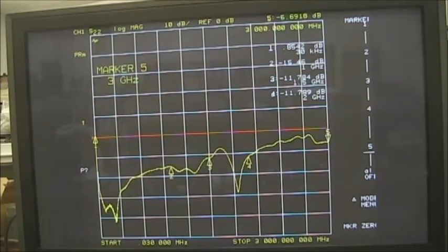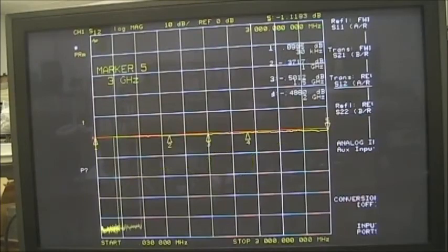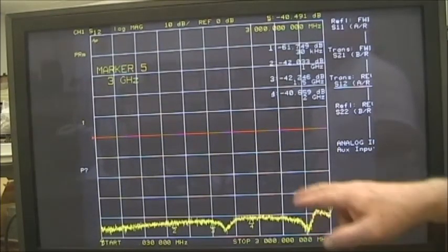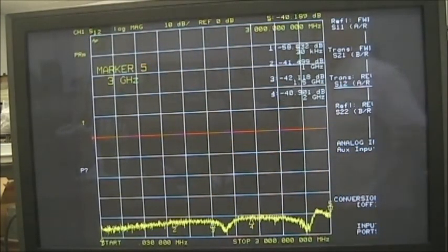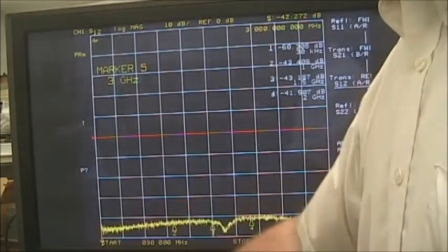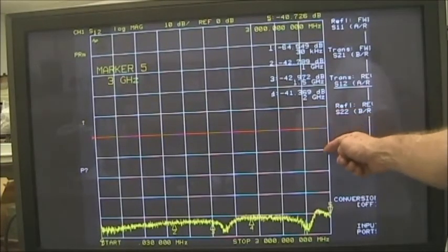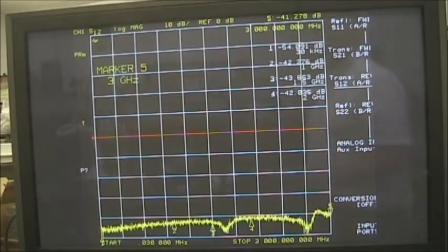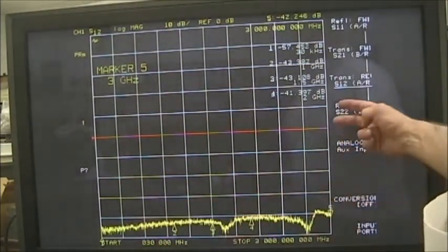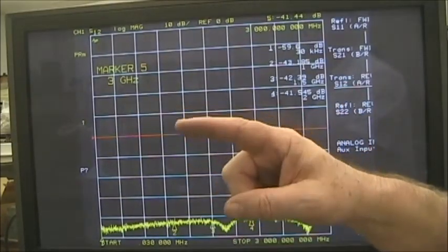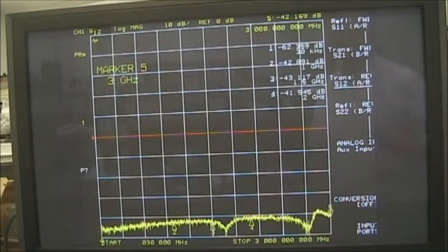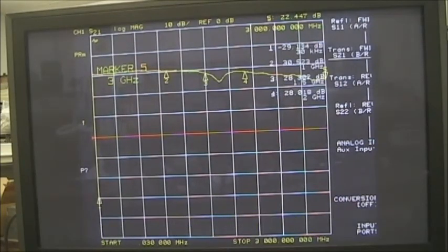S12, which is the interesting one in an amplifier. Now, S12, right? So S12 is the input from the output. And what do we expect? Going back through the amplifier, we expect minimal signal, and that's exactly what we see. We see less than 10, 20, 30 dB of signal getting through, so that's really kind of noise, almost 40 dB. So this amplifier is behaving very unilateral, meaning it's sending data from the input to the output without much feedback signal. Again, there's our gain.